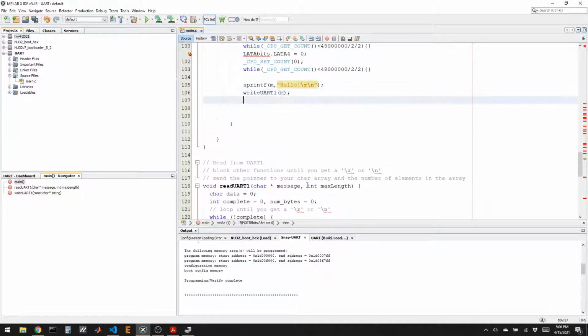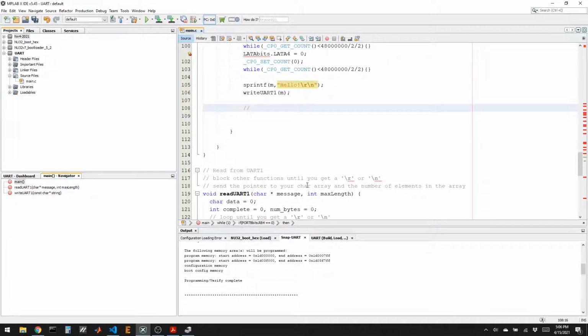Okay, now if you're on Mac or Linux, you need to figure out what is the name of the COM port. So you do that in a terminal window. You would type ls /dev/tty.* to figure out what the name is. ls is the list program, and your port name is going to start with /dev/tty., I think. And then it's going to list anything that starts with that. So the star says, show me anything that starts with this stuff. And it'll probably say USB serial and then some number.